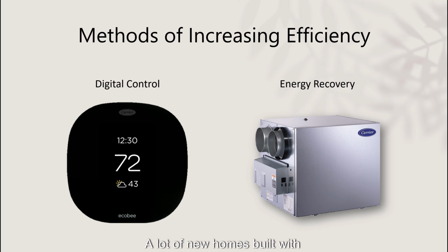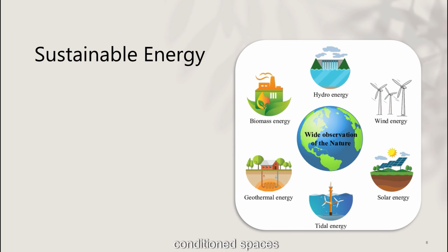A lot of new homes built with the tight construction that they have don't allow for breathing, and that's important, because if we have gaps in our home, we're going to have heat, we're going to have energy escaping. So a lot of these different gaps are sealed off, and with the gaps being sealed off, we don't get fresh air coming in. So that's why we have systems like this installed into new construction homes, or any type of homes that are sealed off with insulation and so forth, like spray foam insulation, making, like, for example, attics, conditioned spaces.